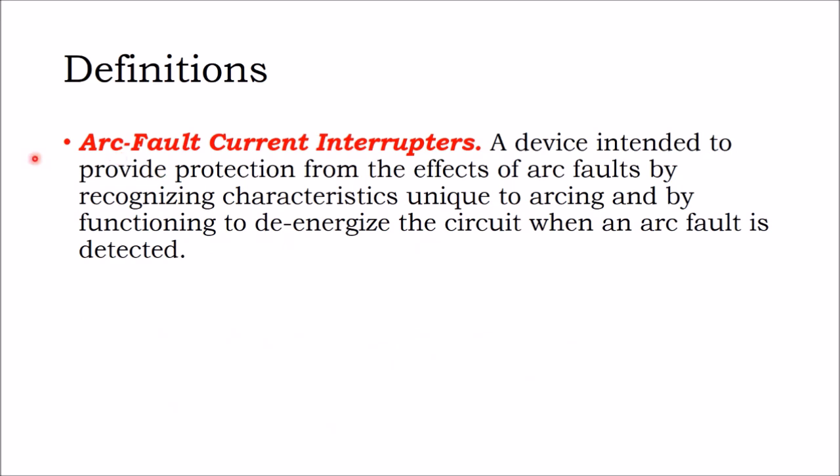With an arc fault, the circuit isn't supposed to be open, it's closed. But instead you just have two wires kind of touching sometimes and not touching sometimes, and there's a little arc that will go across the wires, almost like static electricity, but sustained. And static electricity would be more of a ground fault than an arc fault.